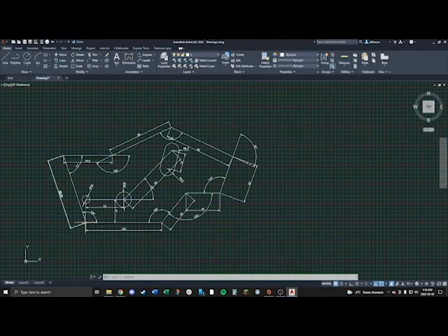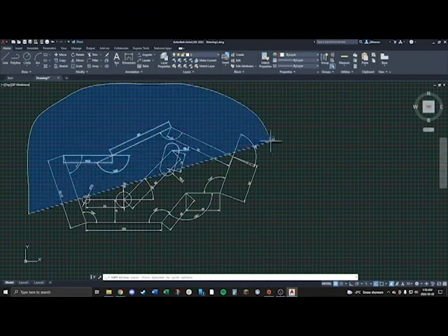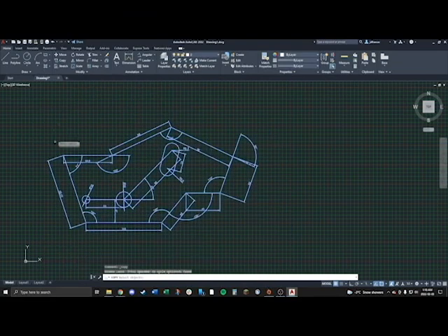If your whole drawing is just starting at the wrong point, you can calculate the difference and copy the whole drawing and move it in X amount. So for instance, if I needed to be 10 degrees lower here, I can just select my whole drawing, hit copy, and select the whole drawing. Enter.